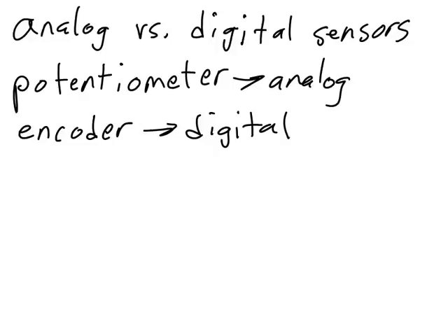In the potentiometer, the minimum value gives something not exactly but close to 0 ohms, and the maximum value gives something that is close to 10 kiloohms. In between those two values, the sensor can have any value, and so the resolution of the sensor is very high. We can detect even a very small change in angle.